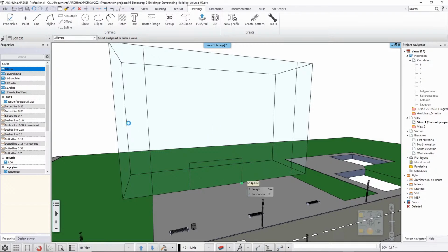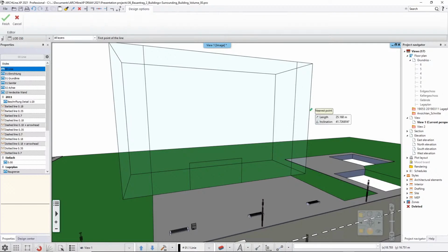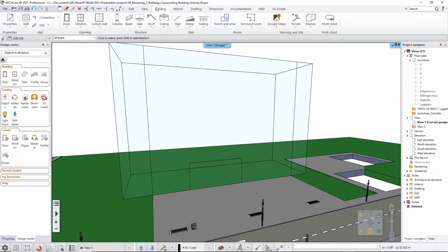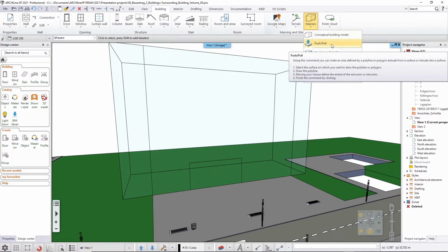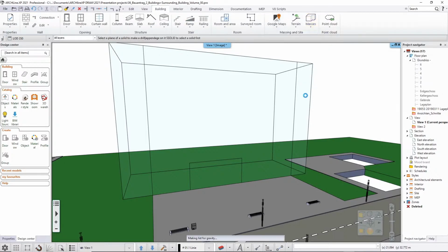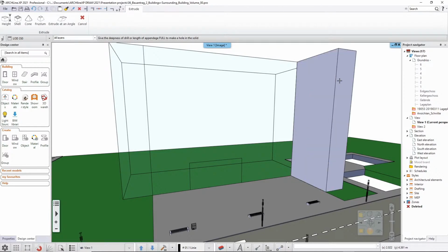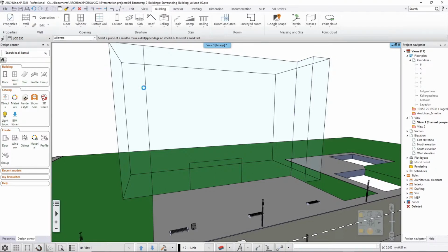And then I will use these for Pushpull to modify the building shape, which was originally designed by building rules, but I can easily modify using the building masses and Pushpull tool. So this is what I do now. I click on this surface. As you can see, the software recognizes the partial surface because I already created an edge over that. When I click there and move my mouse towards me in this direction, I can type a value like, for example, 5 meters. Then I click onto this surface and repeat that with a similar value.